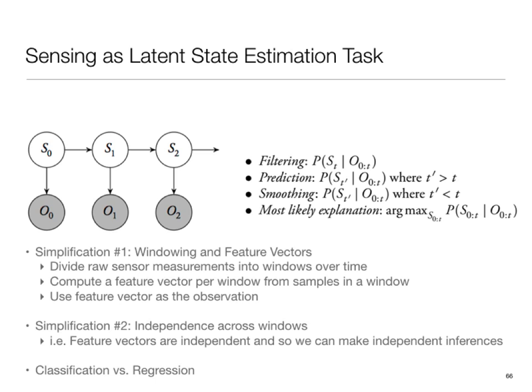So for example, if I give you the ECG signal and you're interested in stress, it's pretty well known from the medical community that heart rate variability is the primary metric of interest. And heart rate variability you compute by looking at peak to peak distance in the ECG. And therefore, if you have that, the rest of the ECG waveform doesn't really matter. So the feature that we would be interested in there would be that heart rate R2R interval, as it's called.